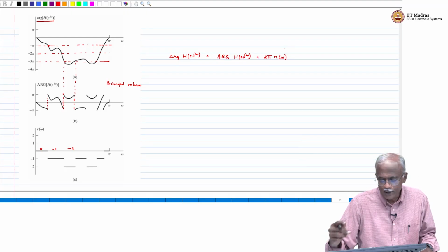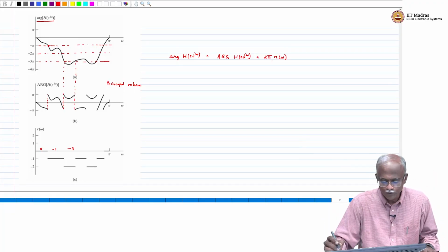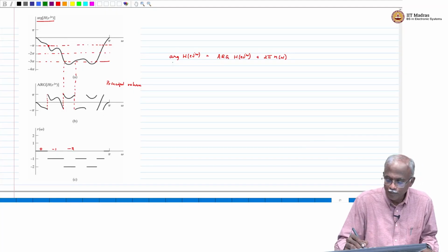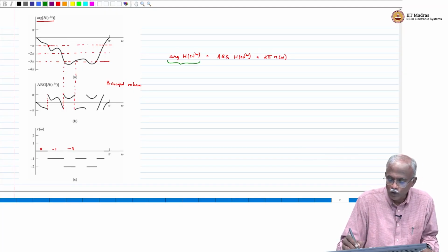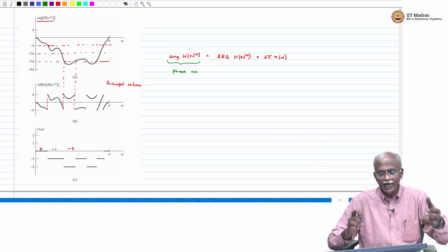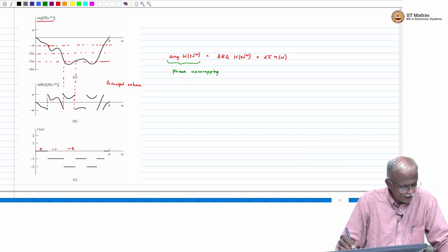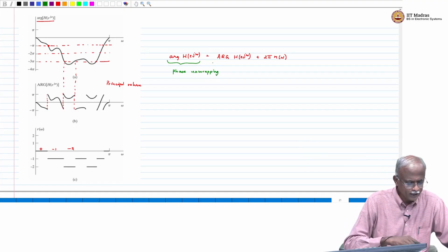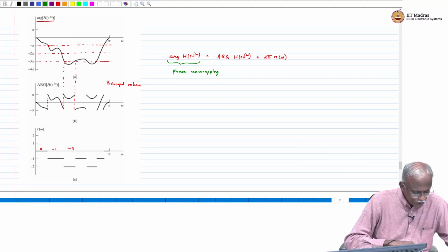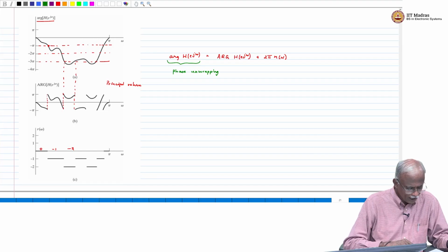R of omega can be plus 1, plus 2, minus 2, basically some addition or subtraction of multiples of 2 pi. This process of computing the true phase from the principal phase is called phase unwrapping. What was wrapped around, you are unwrapping, basically doing the reverse process. This is an important step that we must do in order to get the true, or the unwrapped, phase.